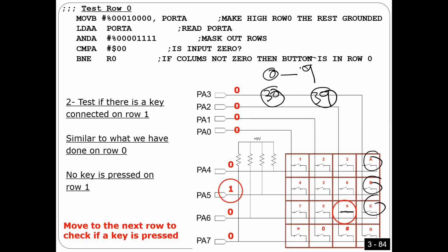Sometimes I need ASCII, and sometimes I need a number, not ASCII, right? Because keypad is going to give you ASCII, how can you get a number? That's very trivial. All you have to do is subtract 30. 30 is hexadecimal, and this one is hexadecimal, right? If you subtract 30 from 30, you get 0. 39, when you subtract 30, you get 9, and so on. Is that okay, guys? So converting ASCII to a number is very easy. So tell us when you need ASCII and when you need numbers, right?